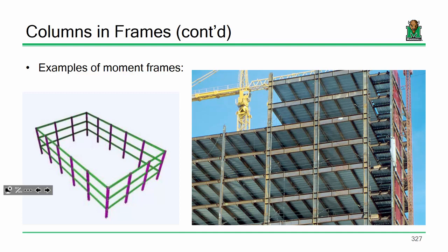Okay. If I was a structural engineer in charge of a major design project, I'm going to generate a few different alternatives, like a moment frame crossing two bays, maybe one crossing 3, one crossing 4, and then do some rough sizing and some rough calculations. Then for each one of those alternatives, figure out, okay, alternative 2, that's the one that's probably going to be the cheapest, and then move on and finalize my design. Actually size the welds and select the number of bolts and do all the detailing. You see what I mean? Is everybody else okay with that?